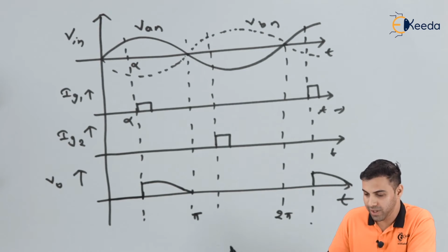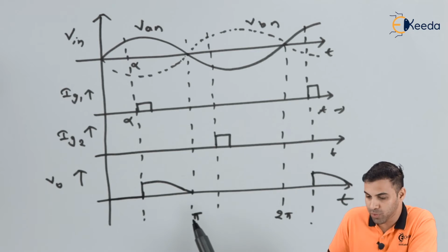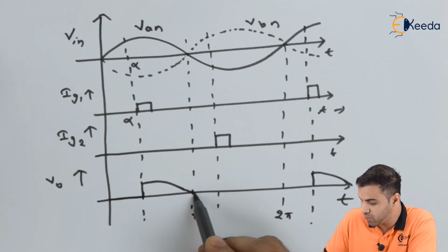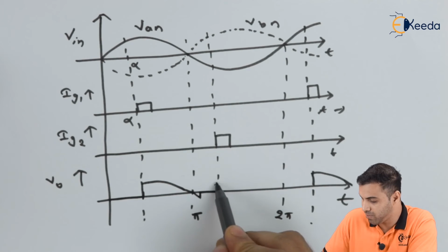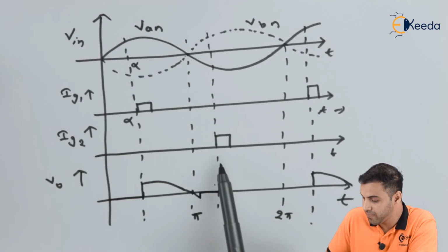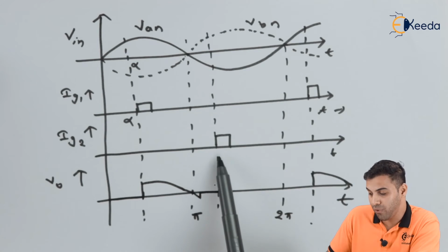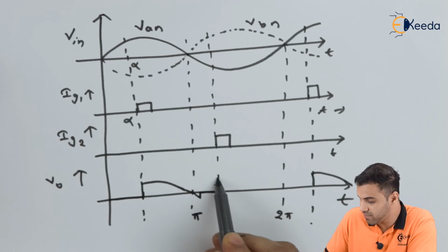So friends, if you can see, the final output waveform will look like this. So this will go a bit further because of the discharging nature again. So this will be the final waveform. Again here thyristor T2 is conducting because we are applying a gate current or a gate voltage to the thyristor T2. So it will again look like this.